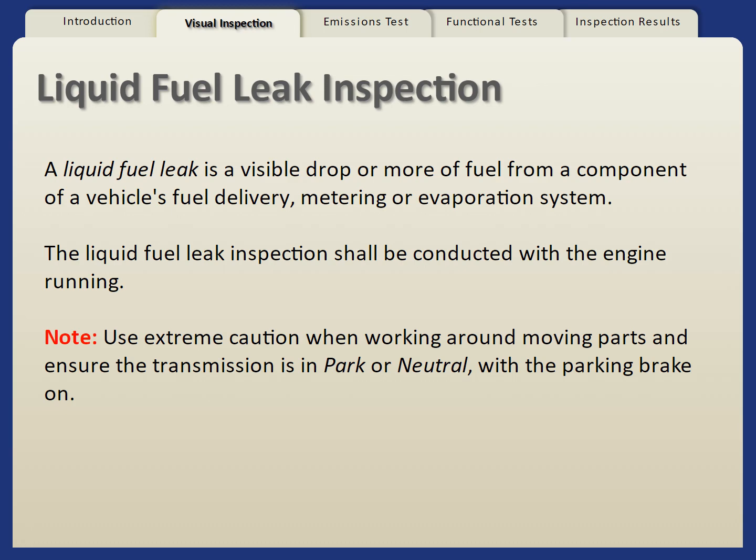The liquid fuel leak inspection shall be conducted with the engine running. Use extreme caution when working around moving parts and ensure the transmission is in park or neutral with the parking brake on.